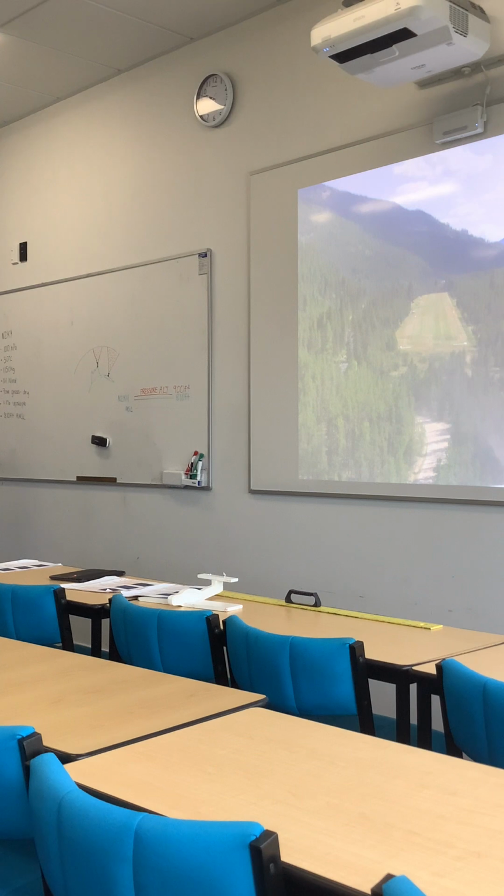So pressure altitude is important. Now take a look at this. This is over in the United States at an airfield that has an elevation of 8,500 feet. It was also in the middle of summer where the temperatures in the States can get really high. So we'd expect the aeroplane here to have a very high pressure altitude. Physical elevation, 8,500 feet. And then the temperature is also really hot. We'd expect the performance to be pretty poor. So this might be an example of where a short field takeoff and landing technique could be employed.